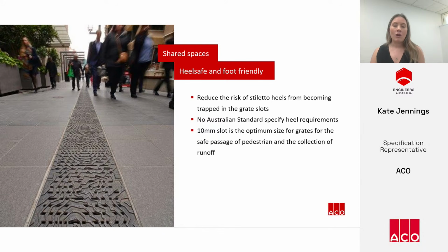Heel safety is a really common complaint from pedestrians, and whilst there's no Australian standard for heel safety, there is an American standard that calls for slots less than 8mm. But there's a trade-off here between hydraulic intake and heel safety. So we don't want to see extremely narrow gaps that, whilst they are heel safe, don't actually collect much runoff, and the drain becomes more prone to blocking up. As a result, at ACO, we lean to a guideline of 10mm and less constituting a heel safe grate.